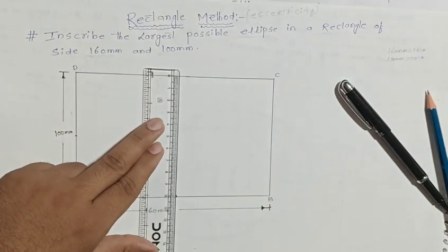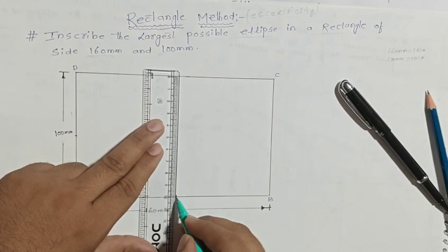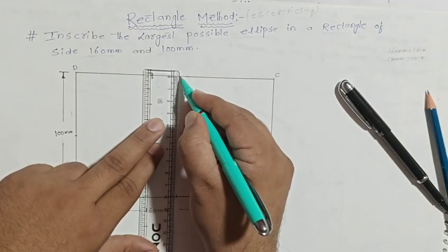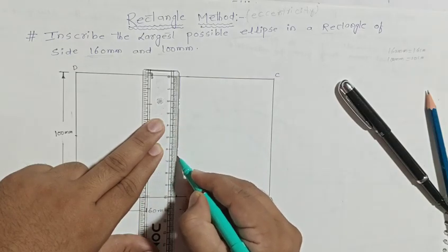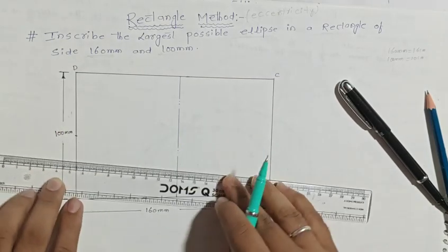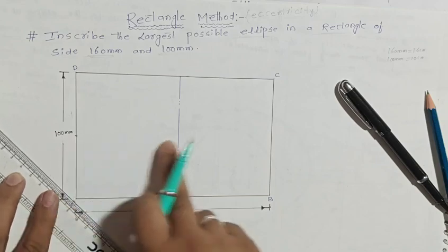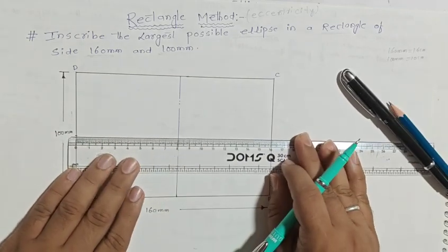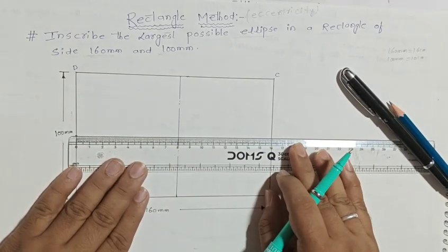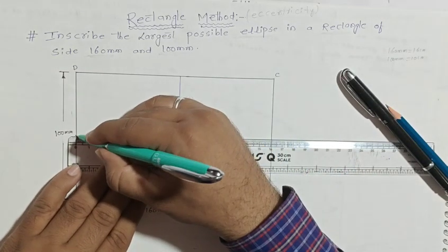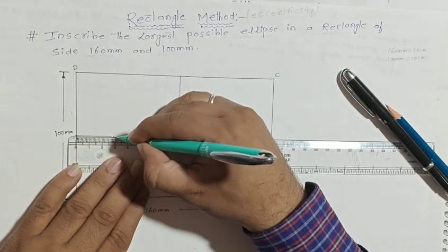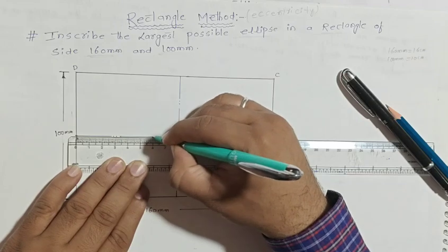First draw the axis. Long line, two dot, it represents the axis. Draw one vertical line and draw the horizontal line. Same, we represent the axis by long line and two dot.